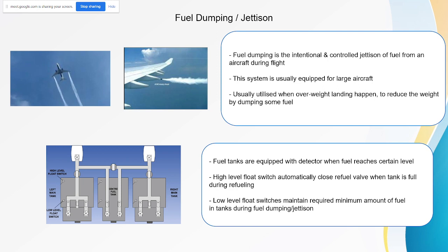This system is usually equipped on large aircraft. It is not commonly used and not usually equipped on small aircraft. The difference from defueling is that jettison is done during flight, and it does not drain all the fuel, only until an adequate level. Usually, it is utilized when an overweight landing happens, to reduce the weight by dumping some fuel.